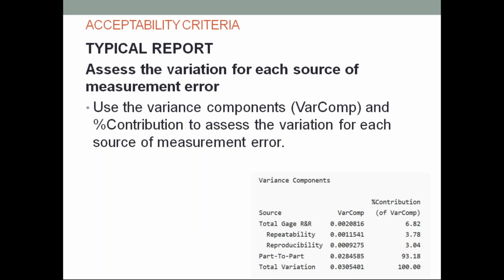Assess the variation for each source of measurement error. So you use the variance components, var comp, and percent contribution to assess the variation for each source of the measurement error. For example, this is Minitab. So you see the var comp down there, which is the component variation.